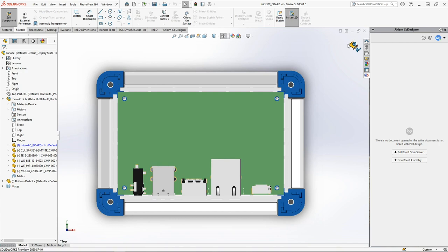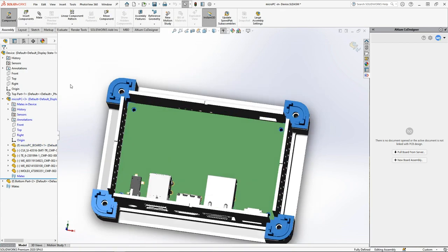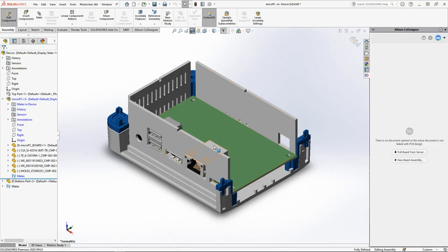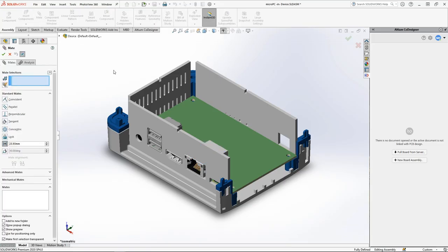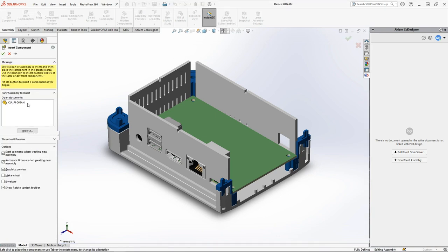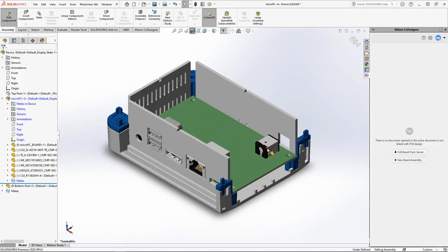The mechanical engineer, for his part, can change the position of any components on the board, adjusting them to the design specifics. Now, this connector does not correspond to the cutouts of the device enclosure, but the problem can be solved very quickly. In addition to moving existing components on the board, the mechanical engineer can add new models as well. In a further push, they will be converted into Altium Designer components and will be placed with the appropriate footprint.